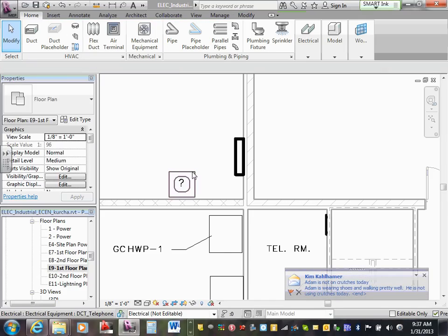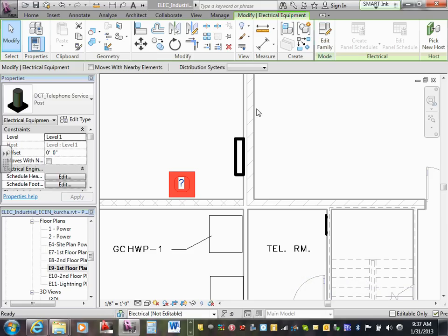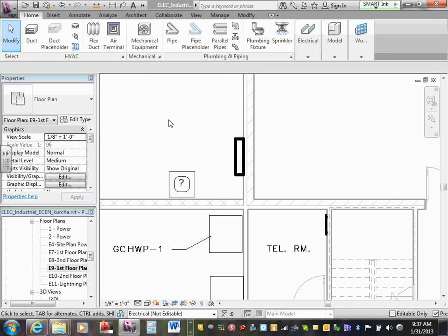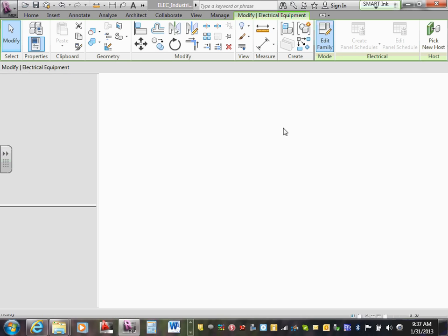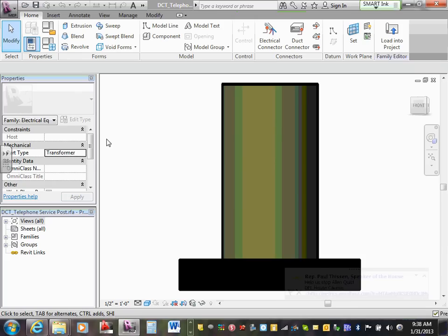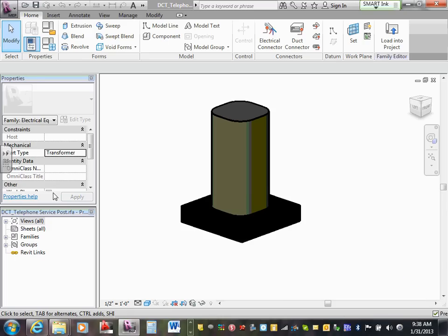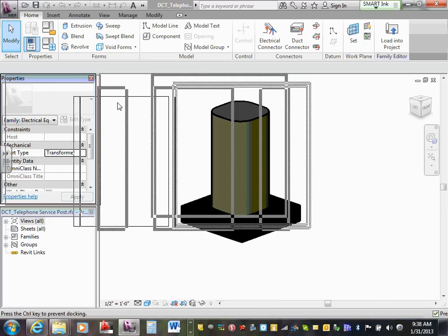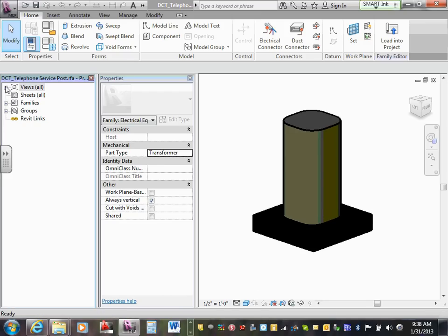Okay. So you guys want it physically smaller? Yeah, physically smaller. Yeah, they wanted to, we were able to, yes. So I'll open up the family. Have you guys gotten into here, the edit family button? Yeah, messed around with this a bit. So I kind of shrunk mine, click on there, we can shrink things down. In the past, we focused on just doing the electrical one, adding a component, changing the parameters, but we really did not mess with the physical dimension of the fixture.